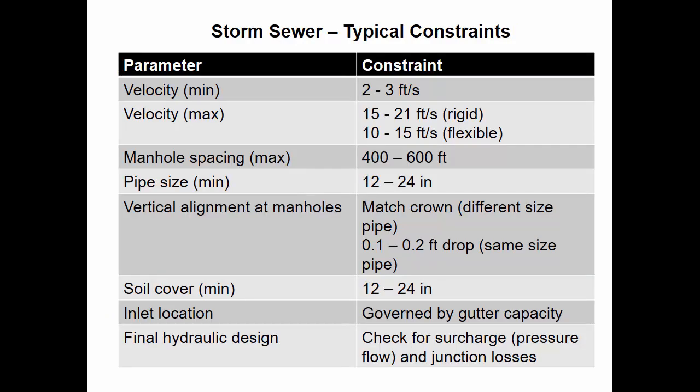All right, so here's a tabular summary of some of the rules of thumb as far as minimum and maximum velocity, typical pipe sizes in a storm sewer, and the spacing of manholes that you'd want to see to make sure that there's easy access to pipe segments. Occasionally it'll be important to inspect and maintain storm sewers, and so the manholes allow cameras to get down in there, or they can put in pipes to send a huge surge of water to kind of flush everything out. So manhole spacing is important.